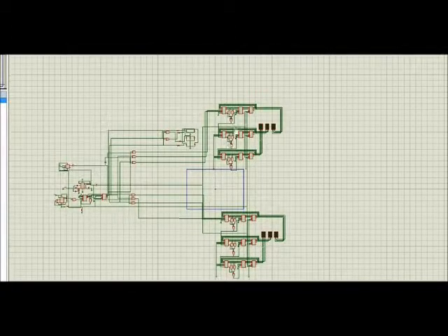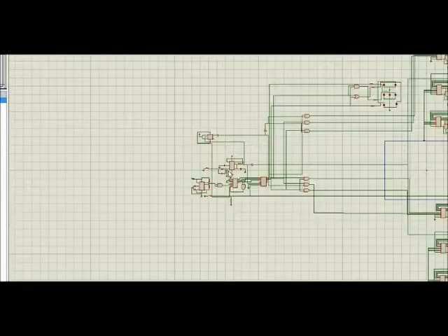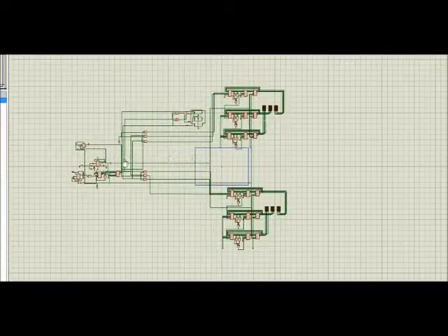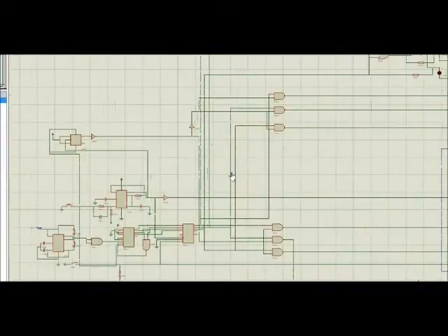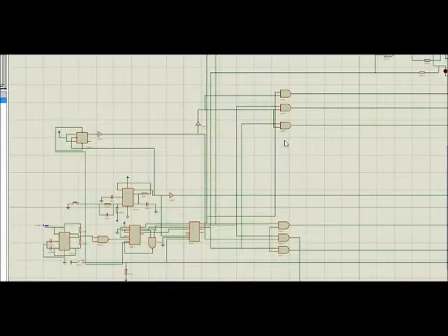Now, as there are 2 players in the game but only one random number generating circuit, the obvious question is, when the game switch is pressed, how does the circuit decide which player gets the new point? To control this, we have placed another part before the adder circuit. This part again is divided into 2 segments, each with 3 AND gates. Let's call them segment 1 and segment 2.